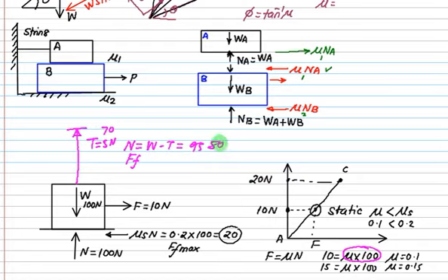So if that is true, then it is 30 Newton. Correct. So what is the maximum value of friction force if we apply one rope on the top side? It is mu static, 0.2, multiplied by 30, and therefore equal to 6 Newton only. Whereas I have allowable force equal to 10. So can I successfully move the heavy body?